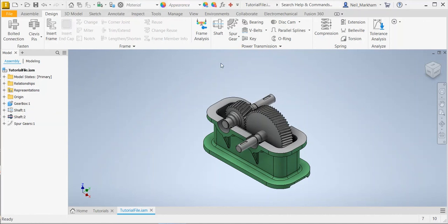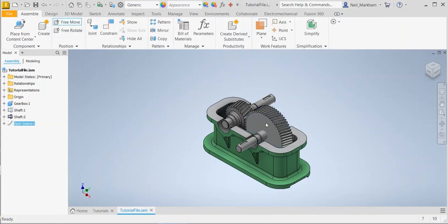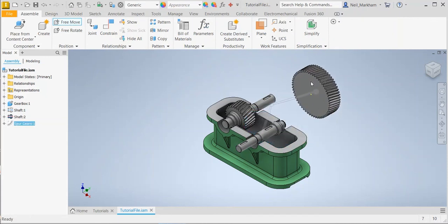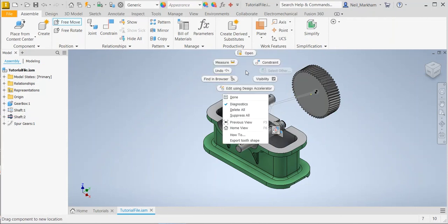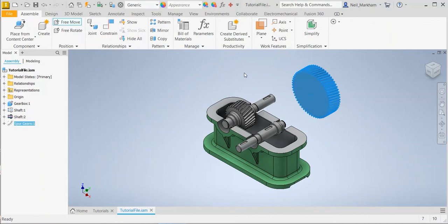What I'd like to do is to add a key between this shaft and this spur gear. So if I, number 1, drag this object away, let's use the free move tool. Drag that object away, you can see that that spur gear doesn't have any accommodation for that shaft. So let's finish the free move tool and just pop that object back into place.